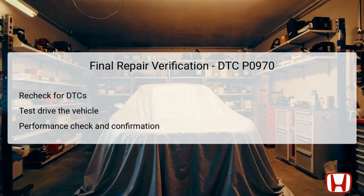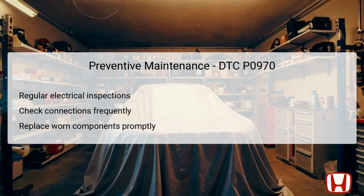Upon completing the repairs associated with DTC P0970, it is important to mitigate the risk of encountering DTC P0970 or similar transmission-related issues in the future. Engaging in regular preventive maintenance is essential. Conduct routine inspections of the vehicle's electrical systems, particularly focusing on connections and wiring harnesses associated with the AT clutch pressure control solenoid valve and PCM. Checking for signs of wear, corrosion, or loose terminals can prevent avoidable faults from arising.